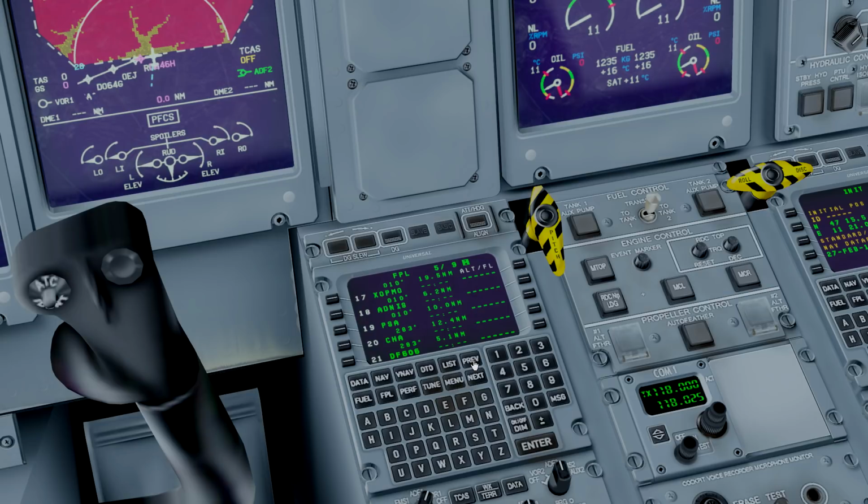But it's basically because this aircraft just climbs using specific speeds, and during the descent you can use the VNAV function in order to calculate at what waypoint I want to be at what altitude, and then I can use the target vertical speed in order to make sure that the aircraft gets down in time. So the VNAV is only really used during the arrival. But just be aware that on the flight plan page you will not actually see the altitudes at which you're going to be expecting to fly different waypoints. Right? So don't worry about that.